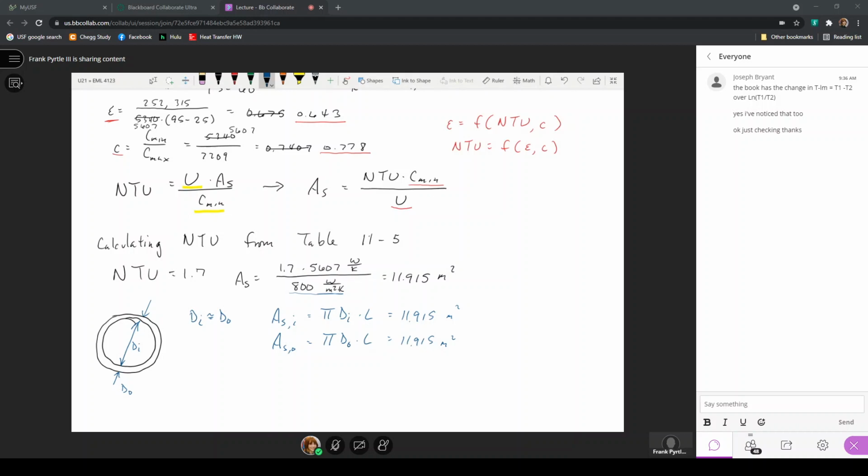The Reynolds number for an internal flow will be the velocity times the diameter divided by the kinematic viscosity. So as I increase the diameter of the pipe, of course, the velocity would decrease for the same mass flow rate, and I would get a lower value of the Reynolds number.